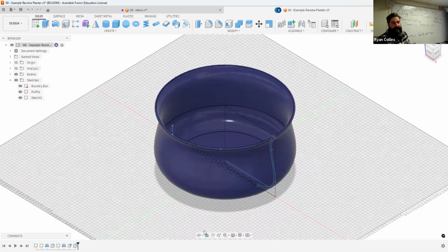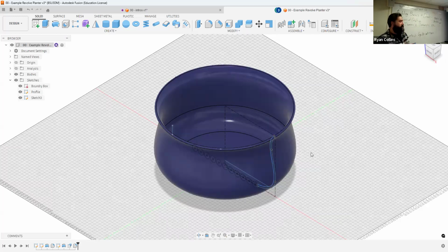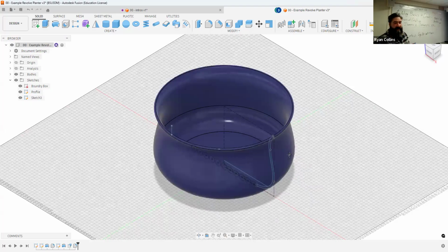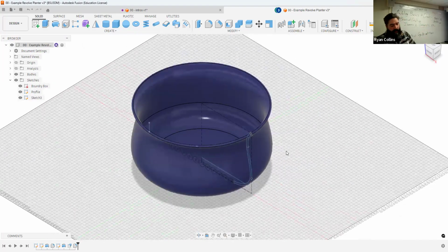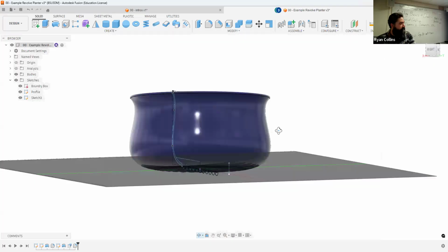The other thing is either with keys or with the mouse. So if you have a mouse, you can use the roller track. So zoom in and out. Press and hold that mouse, and you can pan, which is taking it and just shifting it left or right. Or you press and hold Shift, now press and hold the mouse, you can orbit.